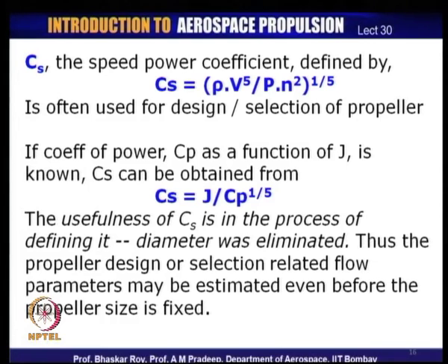This is of course used only by the designers and the propeller selectors. This is because in the process of creating this definition, the diameter of the propeller has been eliminated, as a result of which you have a normalized parameter in which the size of the propeller has been taken out of the equation.